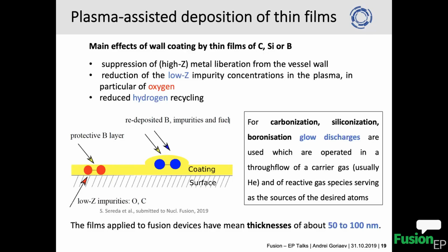So here it depends how long you boronize. You can achieve 200 nanometers, but the time of the procedure should be reasonable. If it's allowed to boronize for 3 days, yes, you can do it. But I think there is a time limitation. Those gases are toxic and there are a lot of safety requirements.